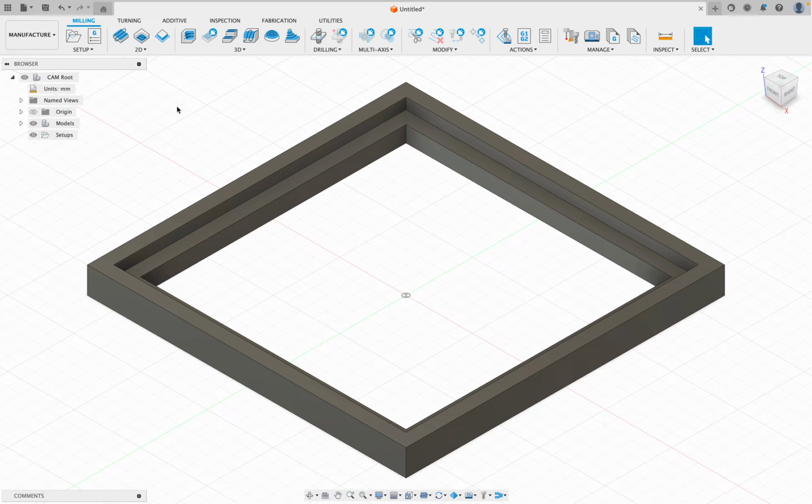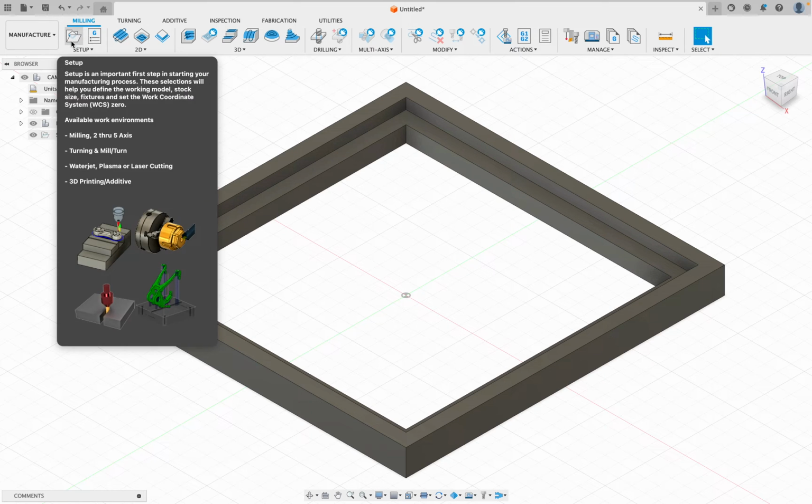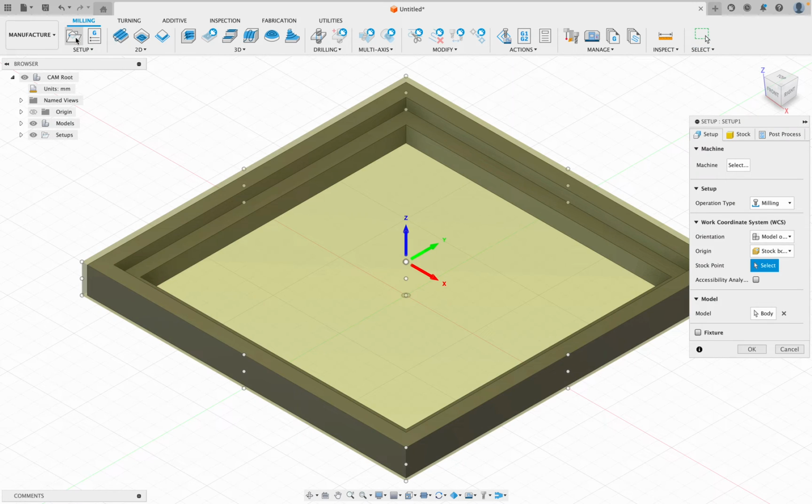All right. So just as we needed to create a new sketch for our object or our project, in manufacture what we'll do is create a new setup. And so a new setup will just help us tell the machine. This is essentially programming the machine. So the new setup allows us to tell the machine, here's how everything is oriented. So we'll hit setup. All right, fantastic, fantastic.